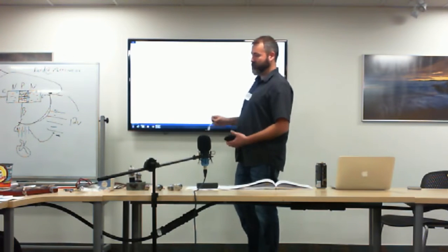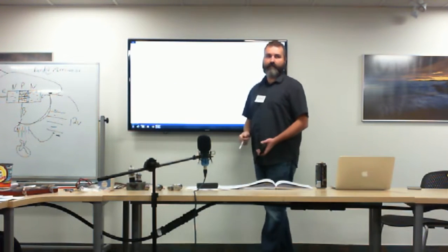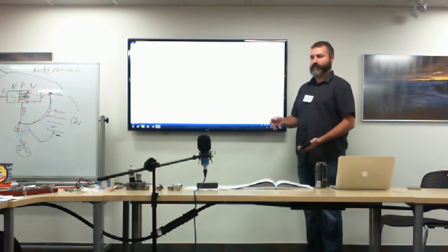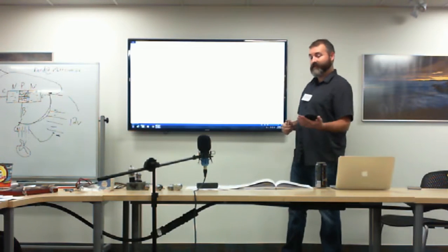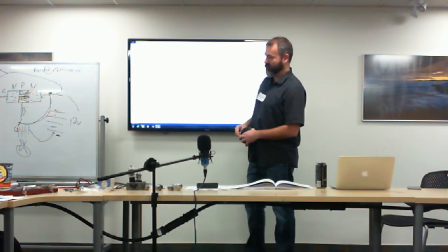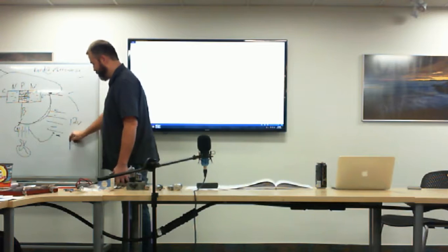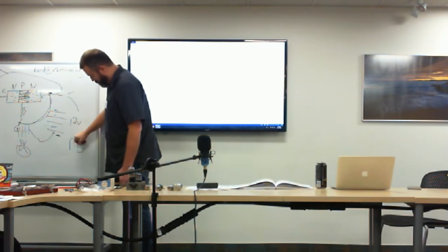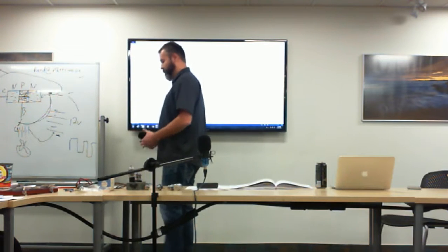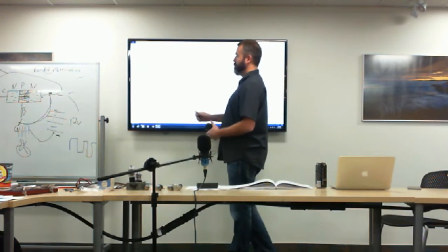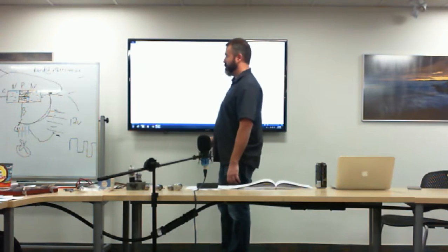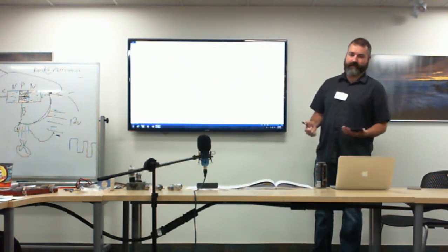In the sense that it's acting as an amplifier, the GPIO pin on the Raspberry Pi can be used to not only do 0 to 5 volts. It can do pulse width modulation, so instead of just going from off to on, it can go in a duty cycle. It can go off, on, off, on, off, on multiple times a second. And by doing that, it'll be turning this switch on and off really fast. And if I do it for, let's say, a 50% duty cycle, it will give 12 volts to my fan 50% of the time. My 12 volt fan will now essentially run half the speed.